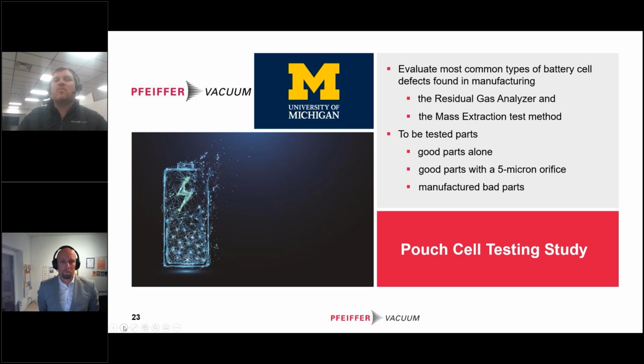Something that's far more likely is that the heat welder that's creating a seal on the outside of the pouch fails at some point, somewhere on a seal or especially where there's a tab, and perhaps the quality control mechanisms on the equipment don't recognize that there's a failure, and you can have a large amount of product that is no good.